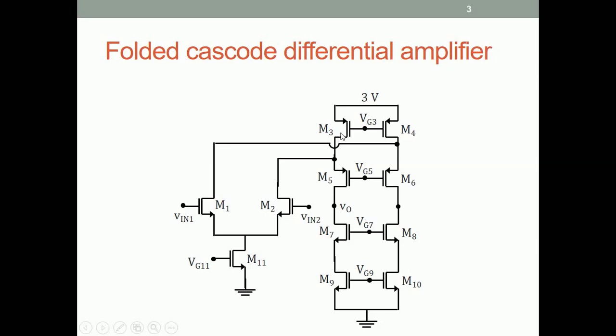And if you recall from our discussion on folded cascode single ended input, there are transistors required at the top to provide the current to both these branches of the folded cascode. The M2, M5, the current is provided by M3, and similarly for M1, M6. Alright, so this is a folded cascode configuration.